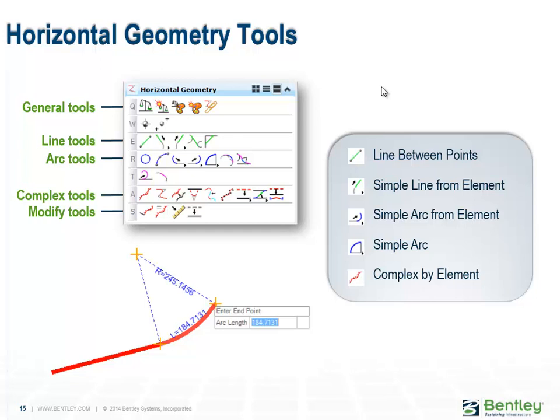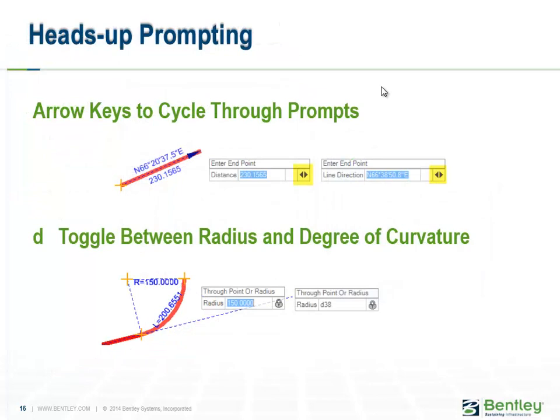The chain commands toggle on the feature definitions toggle bar chains together commands. For example, when using the line between points tool and the chain commands toggle is enabled, each consecutive line automatically starts at the end of the previous line. When enabled, some commands can automatically determine base elements to use during calculations. For example, arc between elements will choose the two most recent elements and set them as base elements to construct its fillet.